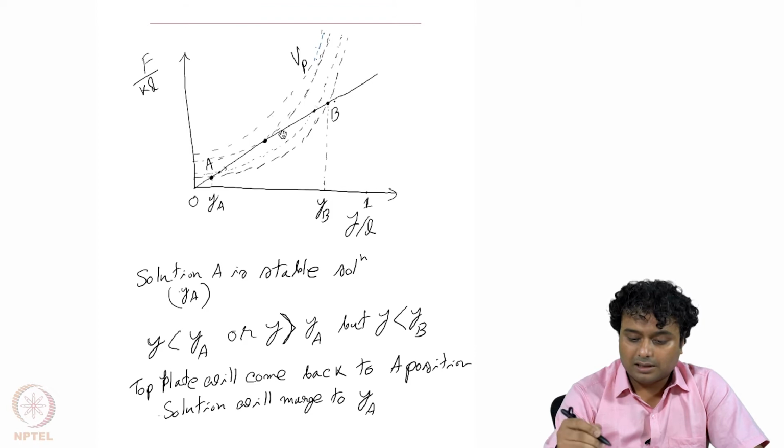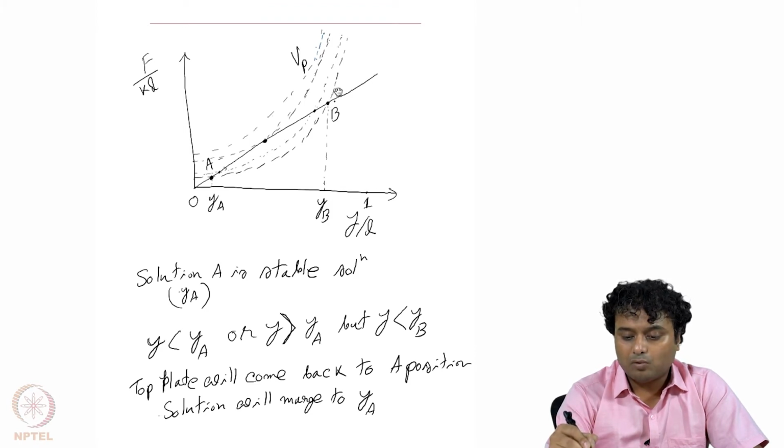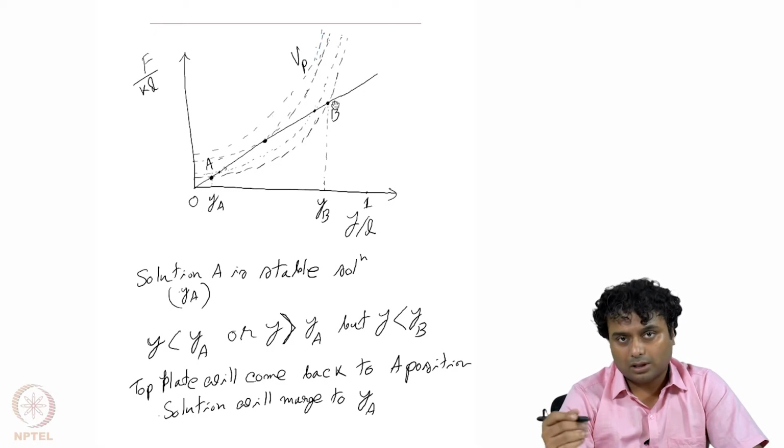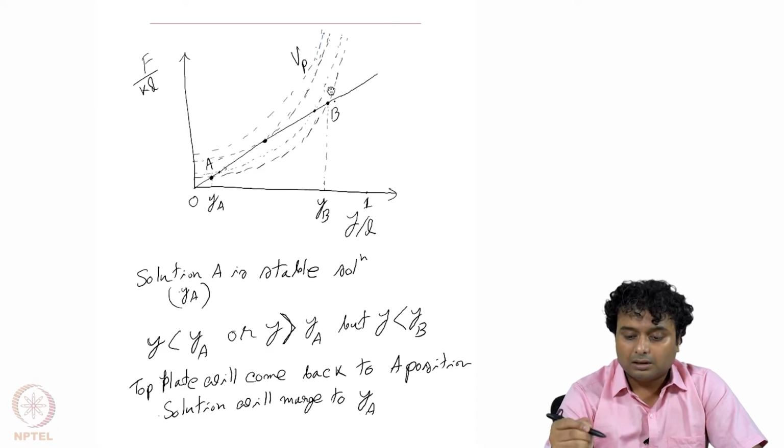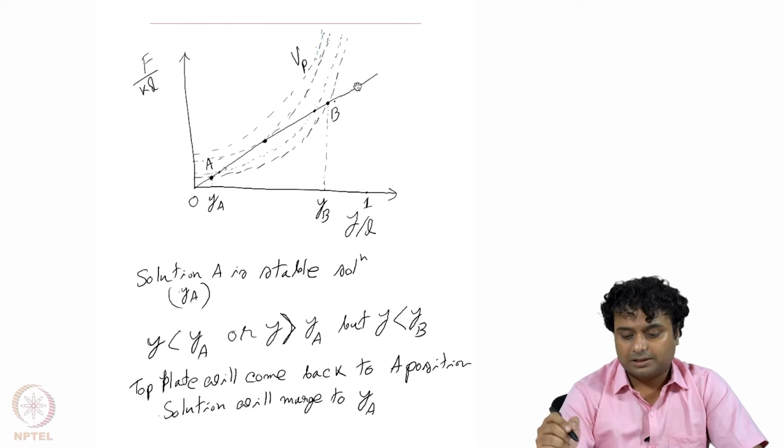We have seen that as we go more and more towards the y equal to d direction, the electrostatic force is getting higher and higher. So the beam, like the plate A, will be pulled in onto the plate B, and this will snap on the substrate.